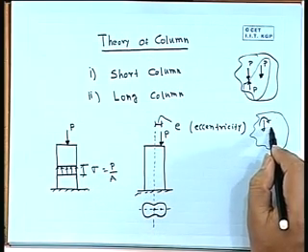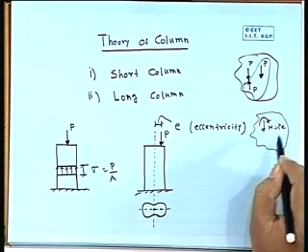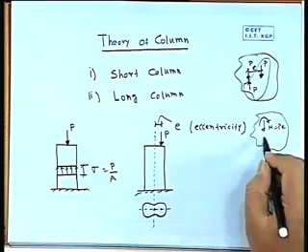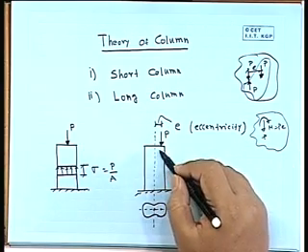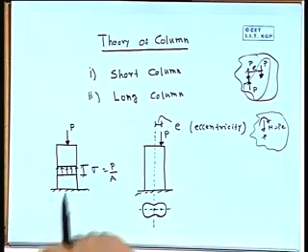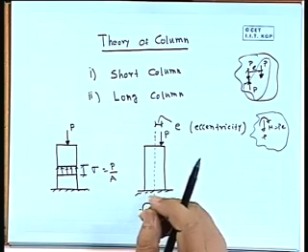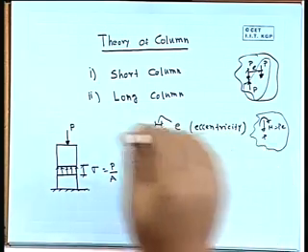is a moment. So, moment is equal to P into E if the distance is E. The force P is not acting at the centroid, it is a little bit away from the centroid at a distance of E. So, we can shift the load to the centroid, but along with the force there should be a moment that will be P into E, right. So, this problem we can just think in that manner.